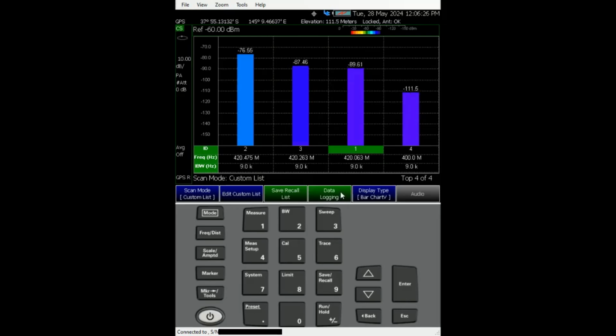After this, we can do data logging. So do a record setting. For the interval, I'm going to use a distance of about 10 meters. I'm going to walk around the building so that if I stop at one point, it won't accumulate like a hive of bees when we try to export it to a KML file. It depends on your situation. Sometimes you want time, sometimes you want distance. For this case, we want to set it to distance at every 10 meters. After this, I'm going out for a record, and then we can come back and revisit the KML file, how it looks.